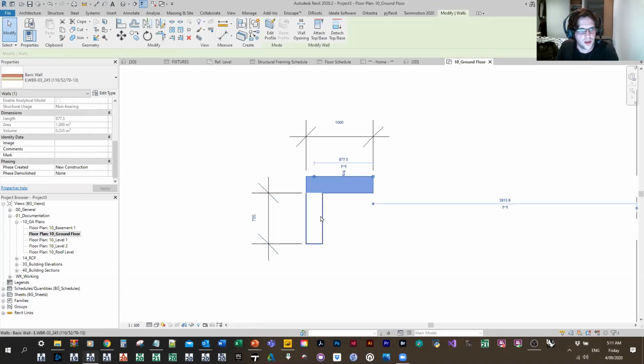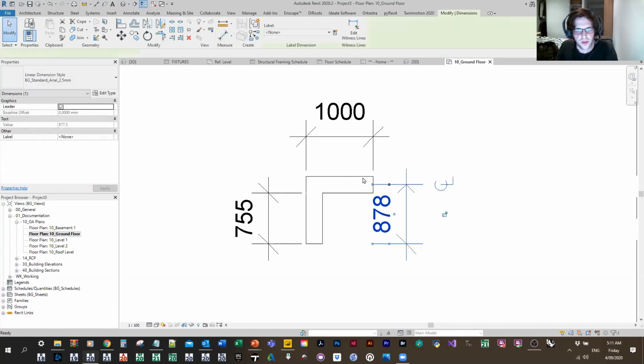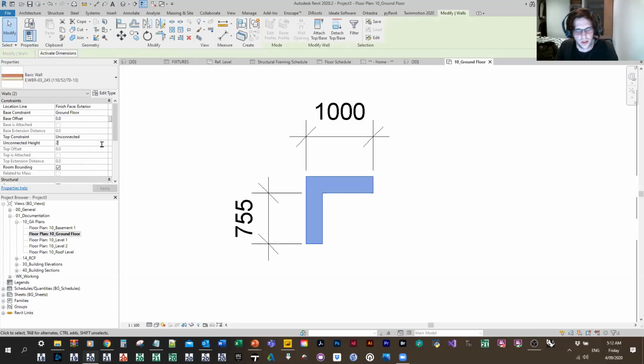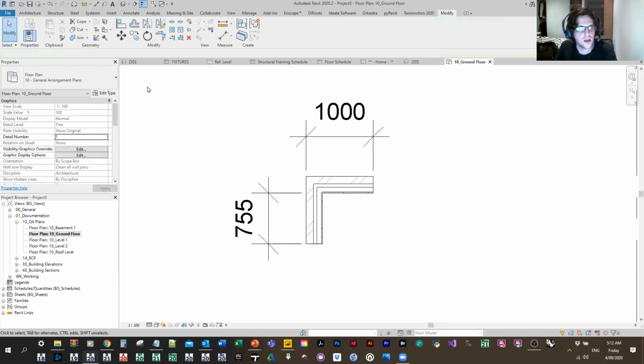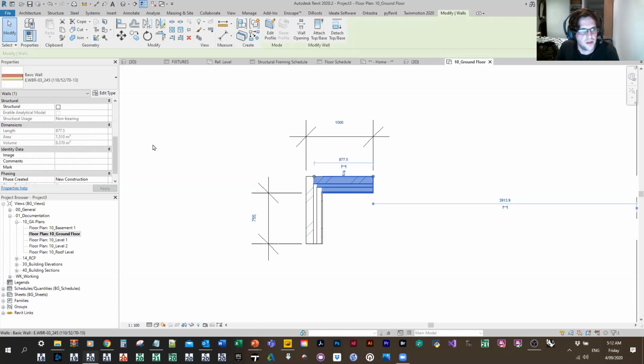So in this case, I think we're going to the center of the join. That's what's determining that 877.5. But in this case, we're actually seeing a bit of hierarchy on this join. So I might actually just make these 2 meters tall so we can see the wall layering. But the way that walls join actually influences how they're costed as well. So if I go to the next condition, obviously I can flip that relationship. And now I'm getting a full report on this wall and a partial report on this one.